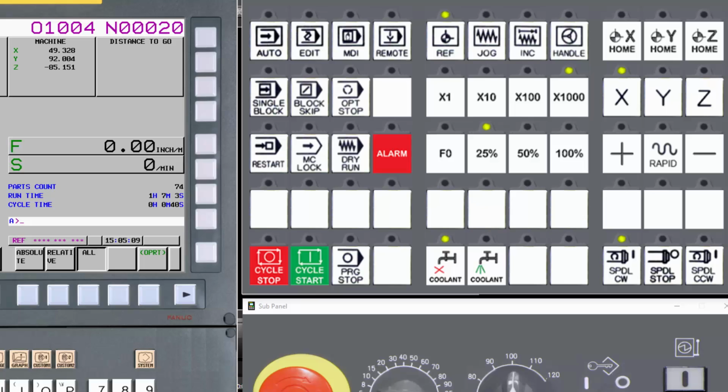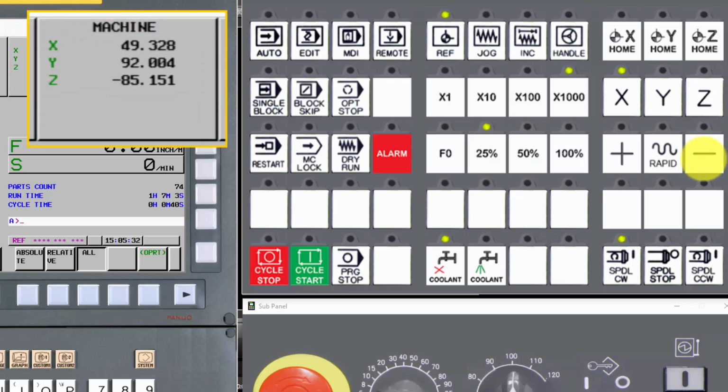It is still a common practice to send all the axes to their home positions before powering down a machine as a matter of good housekeeping. The axis can also be returned to the home position under part program control using the G28 cycle. Some machines have a single button to return all the axes to their home positions. Others are required to return axes one at a time.